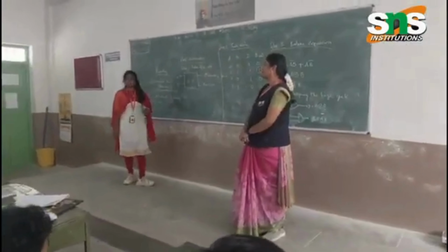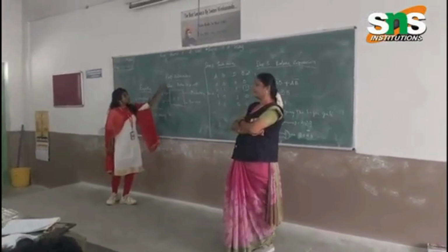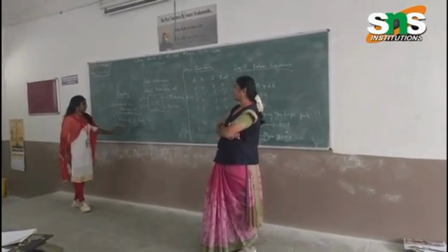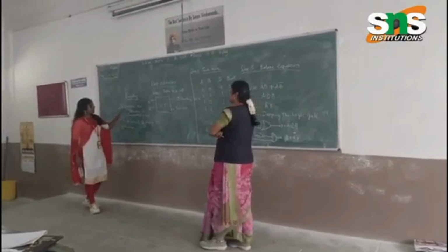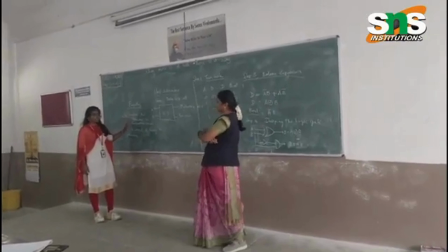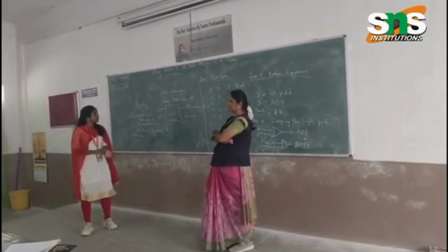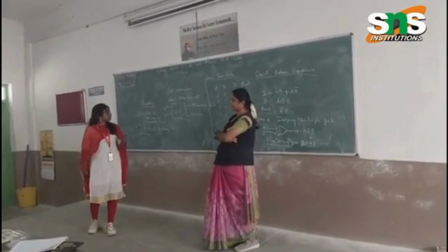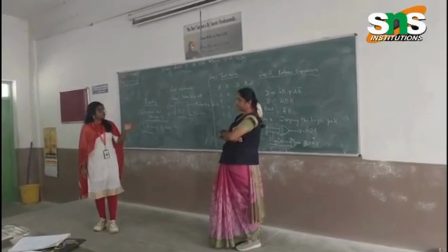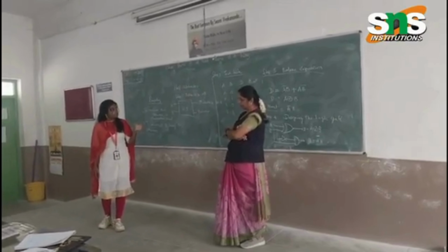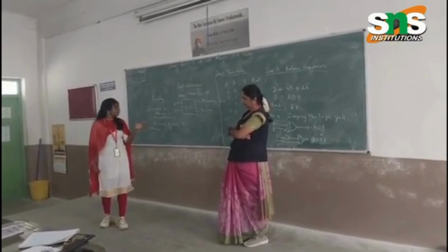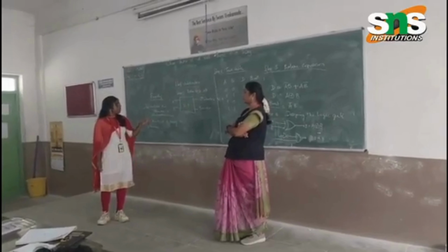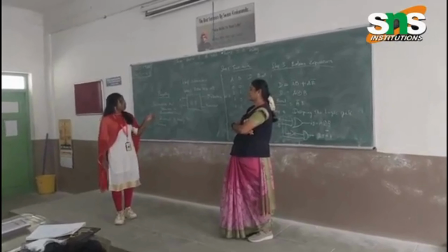So today's topic is the half subtractor. What is meant by half subtractor? It is used to subtract two binary numbers and to perform arithmetic and logical operations in combinational circuits. There are four steps: first, define input and output; then the truth table, the Boolean expression, and logic gate designing. We are using two inputs A and B and two outputs, difference and borrow.